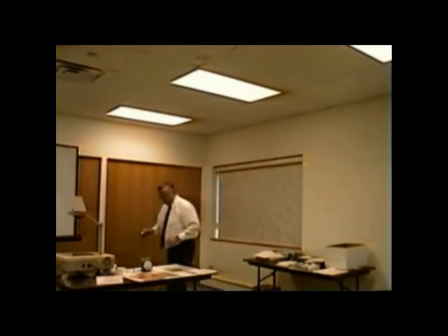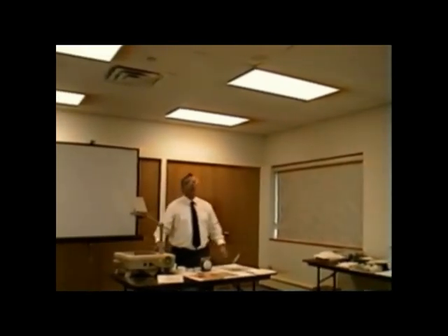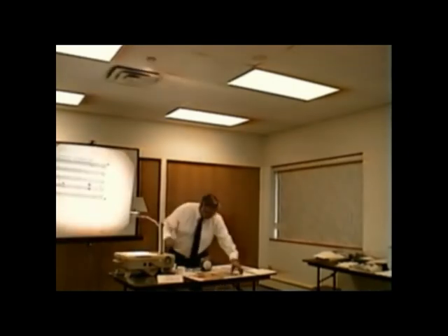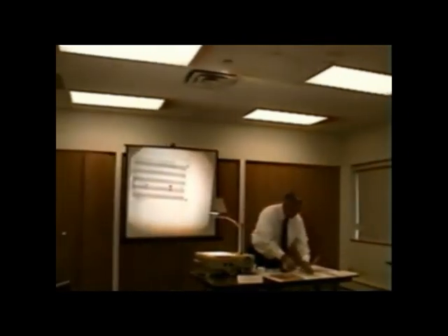So keep in mind, if you call for technical assistance and say that we're going through a lot of heat exchangers, I have an overheating furnace, that's when we will ask you for an external static pressure reading. So let's go finish our last question on the job site.